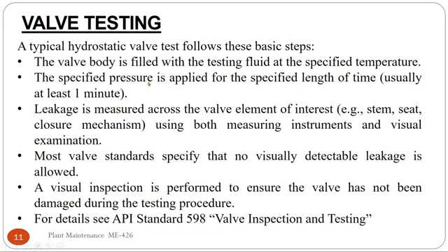The specified pressure is applied for the specified length of time, usually at least 1 minute. First fill the fluid, then apply the specified pressure. Let's say the valve is designed for 200 psi, then the testing pressure is 1.5 times the design pressure. So we have to apply 300 psi and retain it for 1 minute.